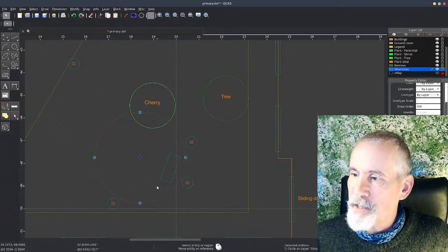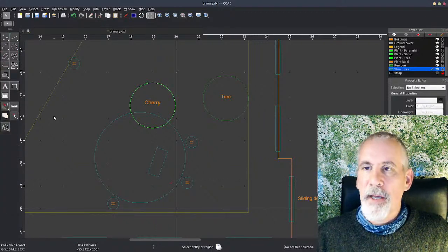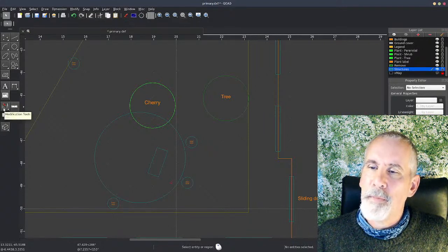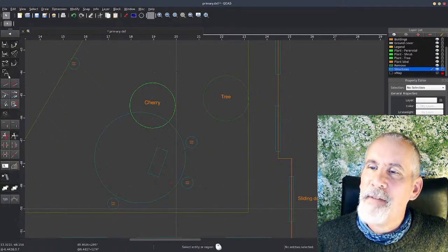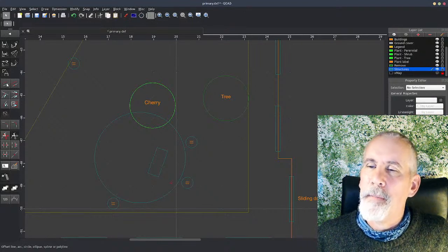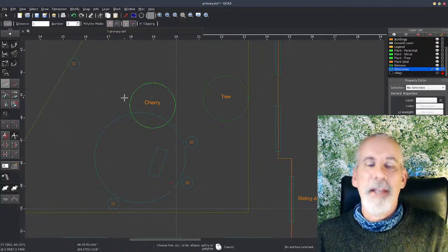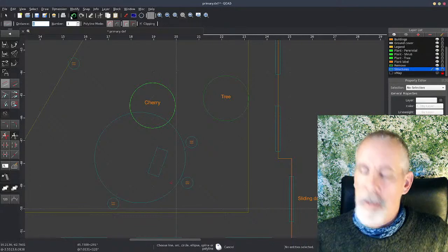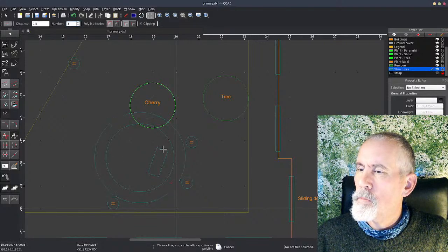So that's fantastic. Oh, and I'll show you very quickly as well. The other really cool feature is offset. In the selection tools, modification tools, bottom left, if you click on there. I never use the menus. I use the shortcuts now, so I find it quite hard to find. Offset with distance, and I think the wall is going to be about 40 or 50 centimeters wide. So distance is 0.5, and the number is 1, and there we go.